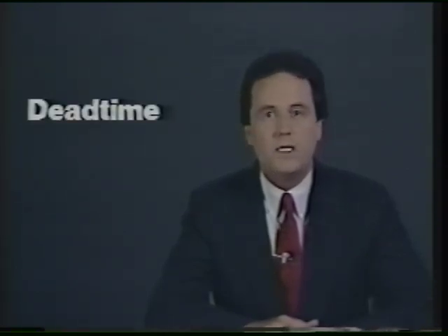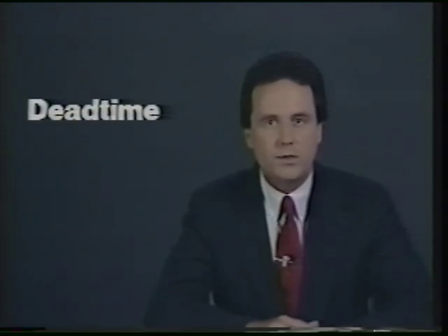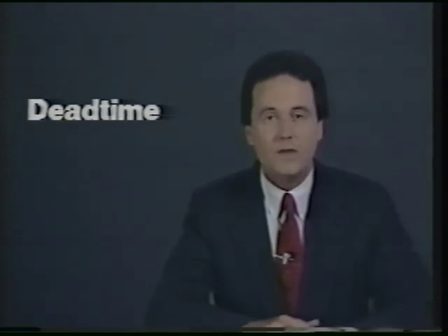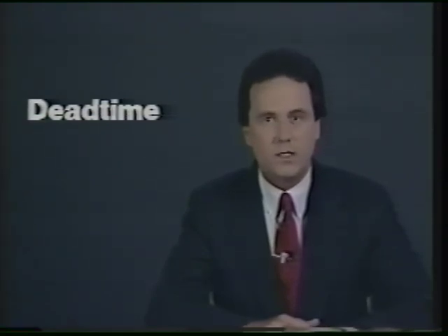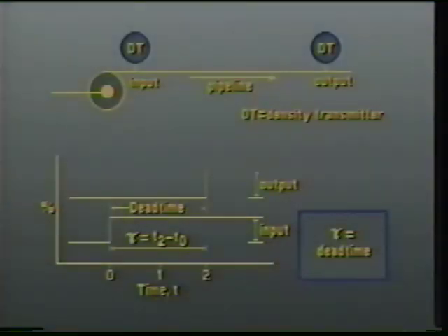The next process factor to discuss in this unit is dead time, which refers to the length of time between the point at which the input to a process is initiated and the subsequent point in time at which the first effect of that change is observed in the process output. For example, here, we initiate a step change in the process input and identify this point in time as 0.